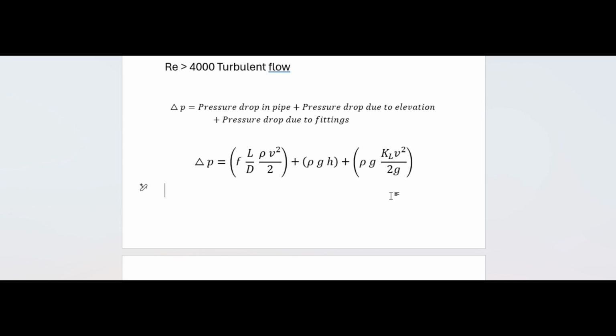You could Google that factor, but for something like 3-inch, it would be like 2.3. So if you have a 100 feet pipe, you could assume that the pipe is 230 feet, and in this case, you don't need to account for the pressure drop in fittings because it should already be built in, and it's more conservative. It does increase with the diameter.